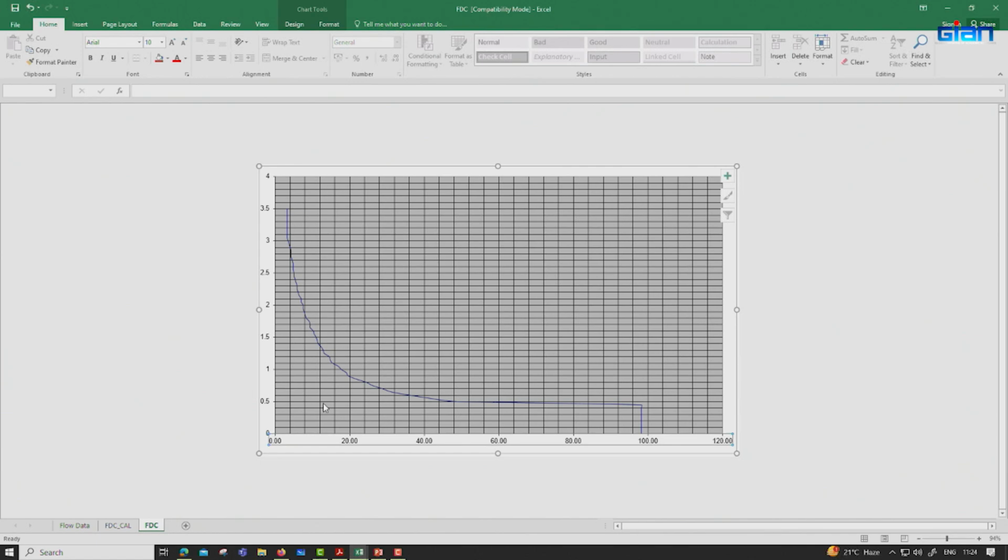And if you select, say, 1 cubic meter per second, you can run about 18% of the time at full load, and for the balance 82% of the year your plant will be running at a lower load than the rated flow, right. That means you have spent money for a higher capacity, but you can use the full capacity only for 18% of the time.